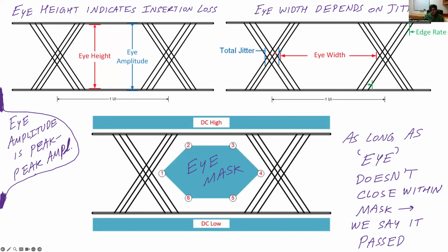And also because the signal can now occur at different times, you're going to have this so-called phenomenon called jitter. Jitter is when you send the signal at the transmitter side and then receive it at the receiver side, the time of arrival of the original signal transition can sometimes be shifted in time because of certain noise in the link, noise in the time of flight or the delay of the link. And therefore, there's going to be some noise which is represented in time for the eye diagram. And this is going to be called jitter. And therefore, this is called the eye width.